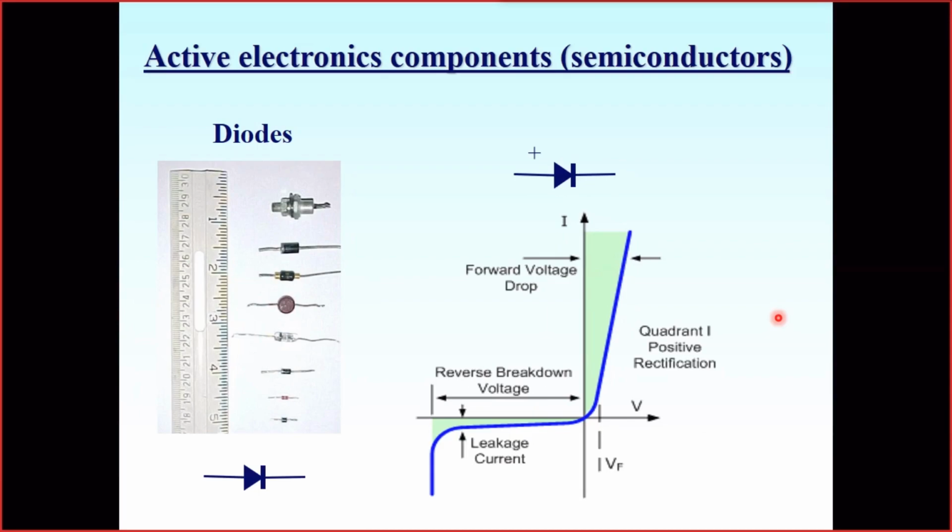Another special type of diode is the photodiode, where we illuminate the PN junction and generate additional current charge carriers in it, and control the reverse leakage current with a light beam. So the higher the illumination, the higher the leakage current will be, and we use such diodes as light sensors.